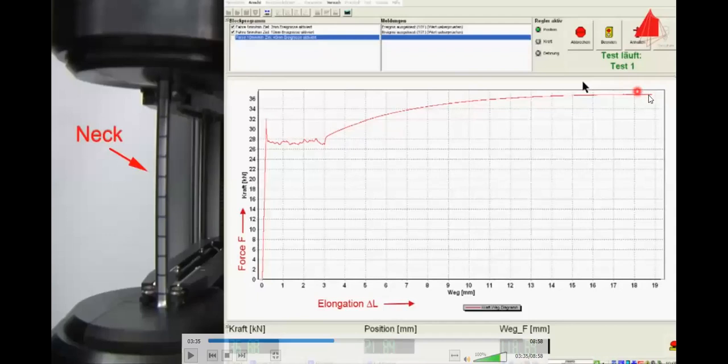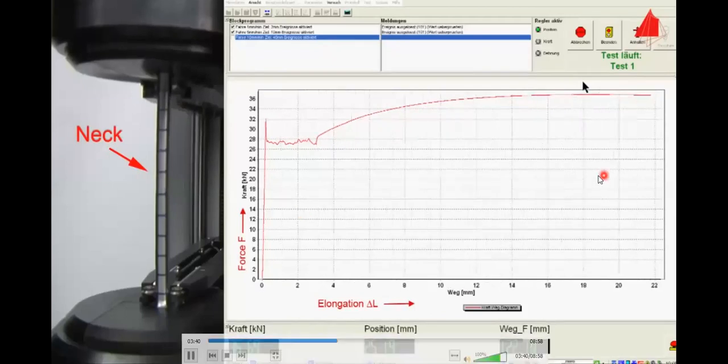So the load increases further, and as we discussed in the procedure, the necking starts after a certain time. Now look at this particular picture on the left side of this video. The necking is going to start where this arrow is showing. You can see here how necking takes place. All further plastic deformation now only takes place at the neck, and eventually the test piece fractures there.